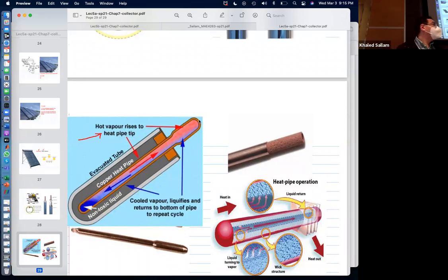So those things connect heat way better than just pure copper. I mean, you could just make the inside copper. This is more effective. How come more effective? Because you are dealing with latent heat, hfg. Anytime you turn vapor to liquid and liquid to vapor, there's huge hfg. You know, in the T-s diagram, when you go from hf to hg, 100 on this side, 2,000 on the other side, kilojoules per kilogram. So every kilogram carries with it 2,000 kilojoules. It's a lot of heat that you can't just pass by conduction, you will not be able to catch up.